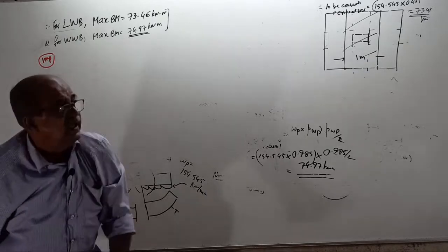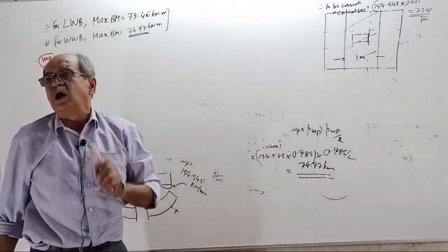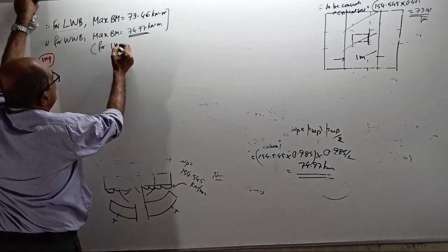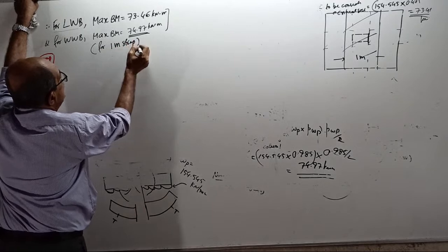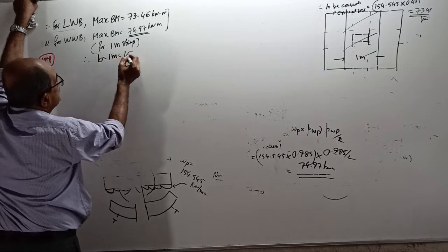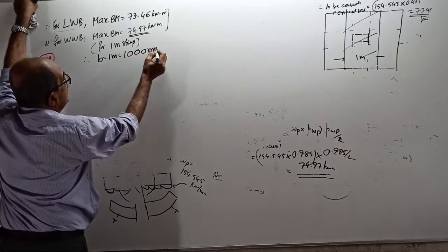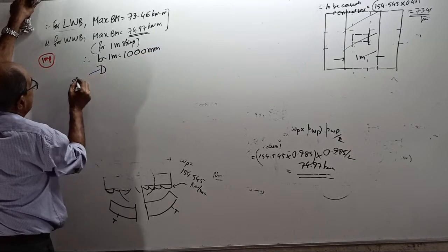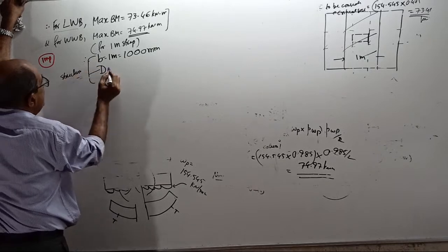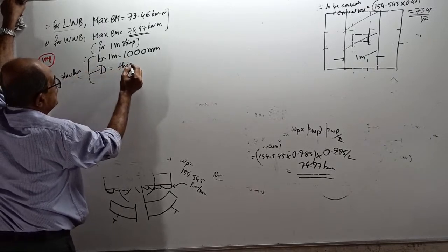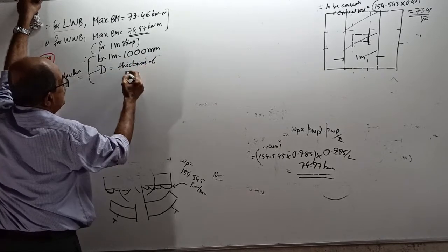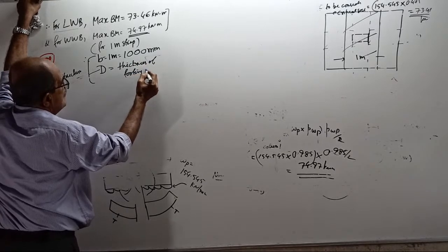Okay, clear. And remember, structural width, how much? The bending moments, both of them, are for a 1 meter strip. Remember, therefore, B equals 1 meter or 1000 millimeter. And remember, capital D, structural. Both of these are structural. Your structural D is the thickness of the footing slab.